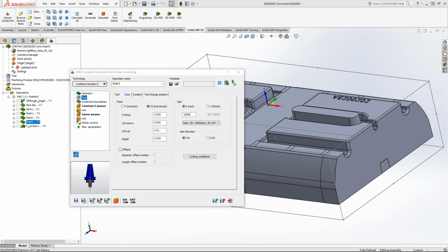For roughing or finishing? For finishing, I really don't change anything as far as step downs. It's all based on my calculation of depths per step, whether it's step over or step down, and what kind of finish I want on it.